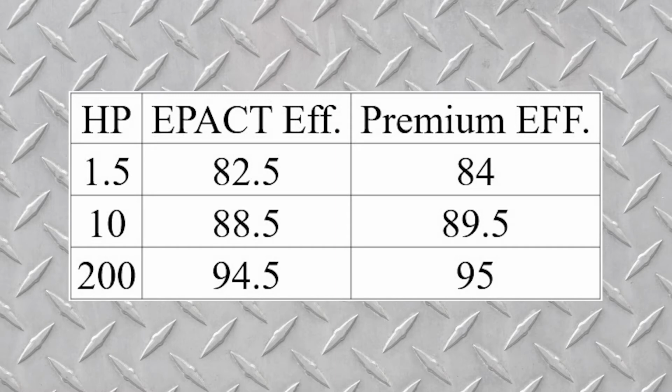They're pretty high. Now, for some of the smaller motors, it can get a little low. For a 1.5 horsepower motor, we're down to an efficiency of about 82%. So you could say there's energy to be saved there. But now you move to larger motors, you can see 94.5%, 95% efficiency, and that's getting pretty darn good. So it's going to be hard to improve on this.